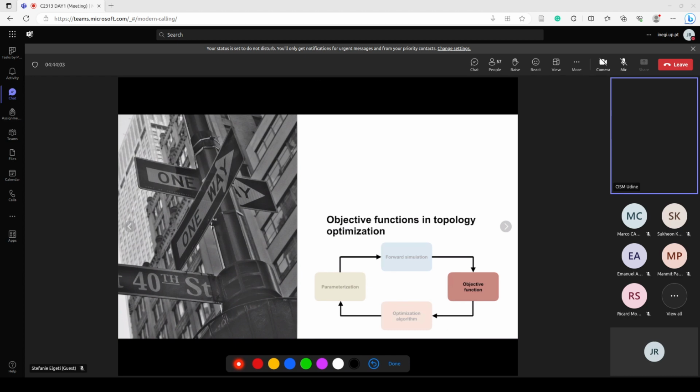Yeah, so the question was about the checkerboard pattern. That on one slide it was said one should reduce the solution set in order to avoid checkerboard patterns, and now just recently I said that if you evaluate more precisely, then you can also reduce this effect. So I think it's a combination of both, basically. If you evaluate very accurately, you can afford a bigger solution set. If you're very coarse, then you need some kind of restriction in order to prevent these patterns.